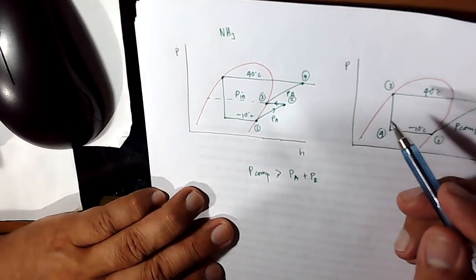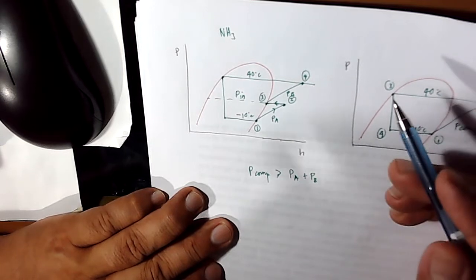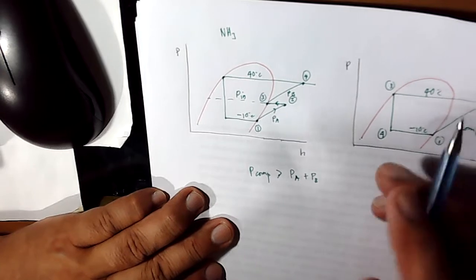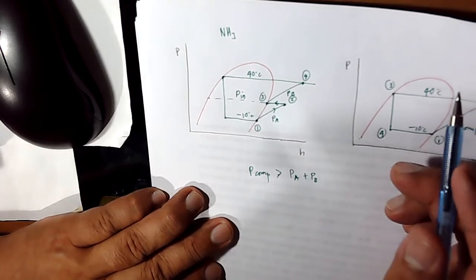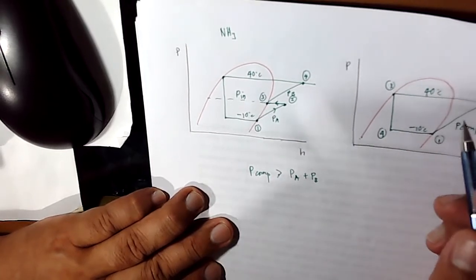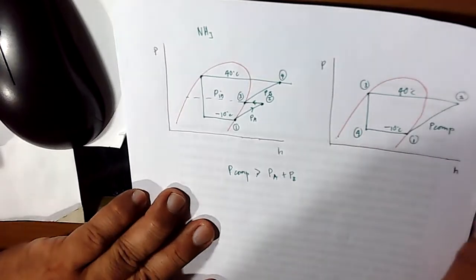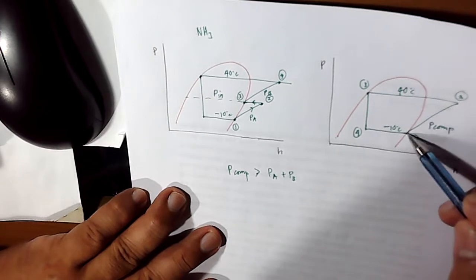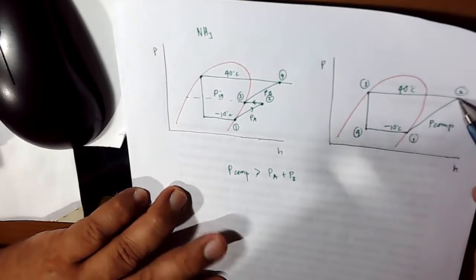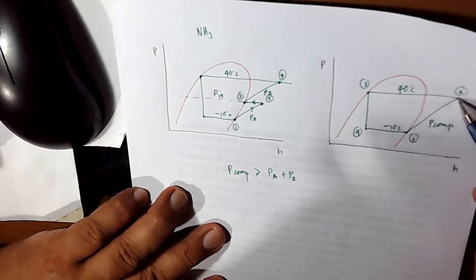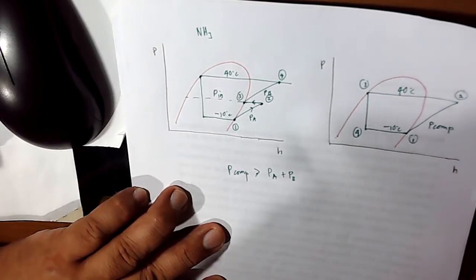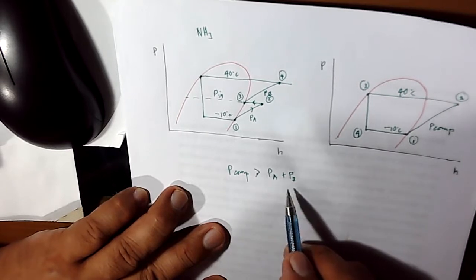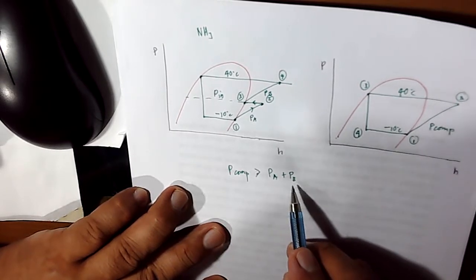Okay, so we have two mediums, no? The refrigerant in your refrigeration system and the cooling medium, which is water, to absorb the heat coming from the refrigerant side. However, if you use only one compressor in a standard vapor compression system, we have only one big capacity compressor, which is the combination of the low stage compressor and the high stage compressor.